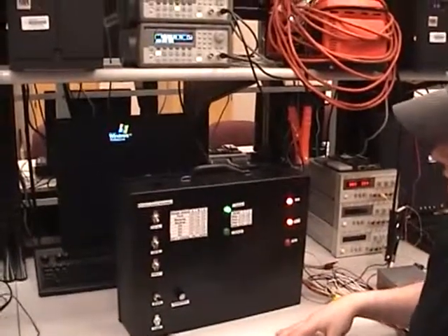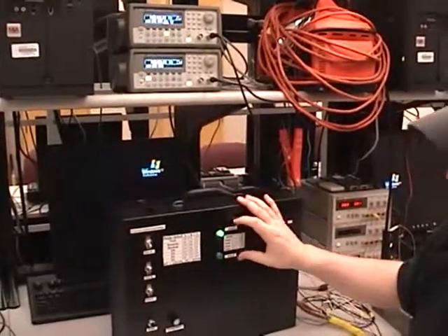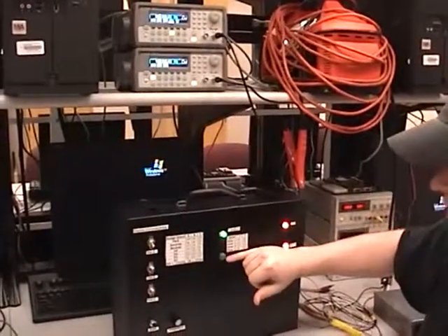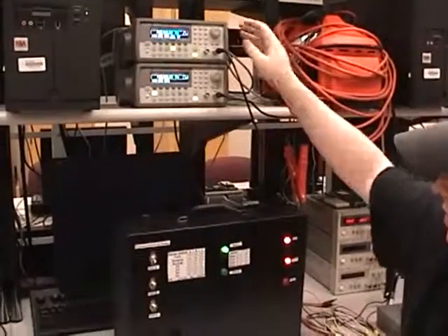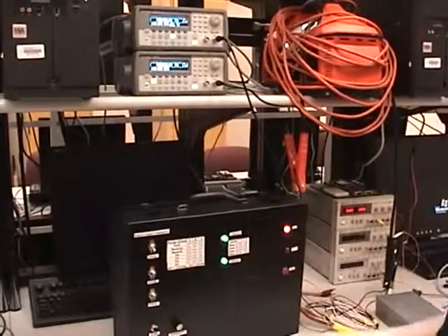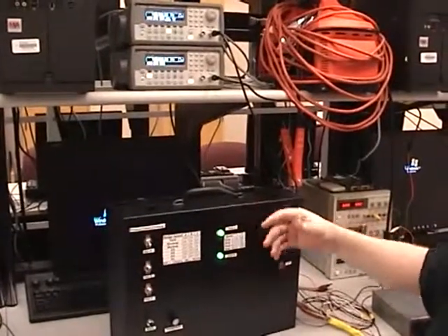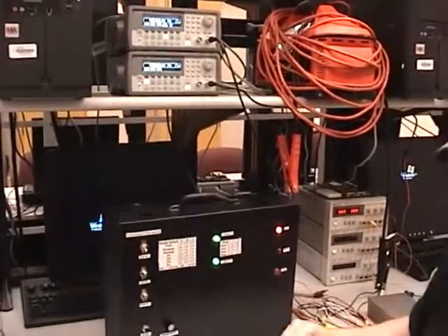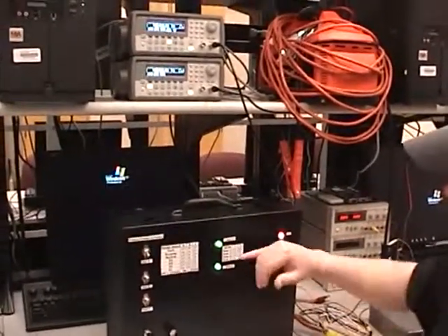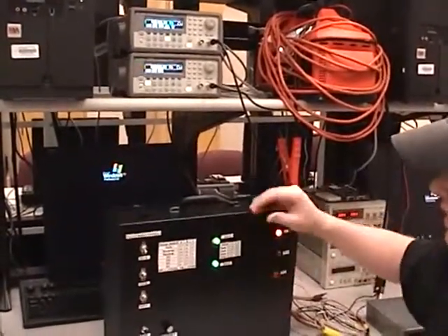and then there's fourth. Now you would think that maybe there's a bad delay or something in the microcontroller, but that's actually something we had to implement. I mean, the microcontroller is super fast with this easy type logic. So what would happen is if the max rev limit was reached and it was currently in first gear, then as soon as we raised it to 500, it would analyze it, shift it to second gear, analyze again, shift it to third, and it'd be so fast that your shift solenoids wouldn't even have time to respond to that. So you would basically get a direct shift from first gear all the way to fourth gear. So there's basically a wait of 3 seconds before it analyzes it again and does that shift based on the distributor.